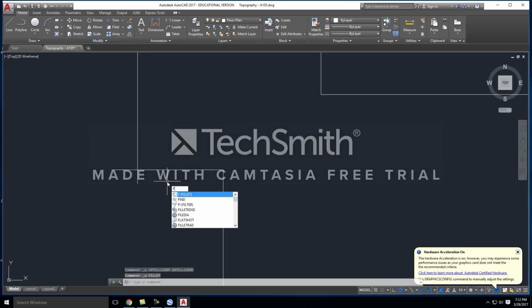Again, I'm going to hit F for fillet, enter. Before I click on the first object, notice down here it says fillet, select first object, or hit U for undo, P for polyline, R for radius, trim, multiple. So it gives you a handful of options on what you can do next with this command, okay?